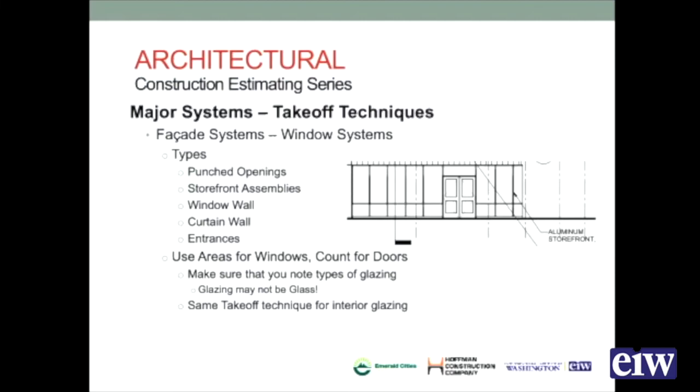Curtain wall is different. It spans on the outside of the building and goes the whole way. It's clipped back to the structure at every floor. And that's how it works differently. It's usually a thicker mullion. So curtain wall may have a 7.5 or 9.5 inch mullion, whereas a storefront may have a 4.5 inch mullion, and a window wall will be somewhere in between.